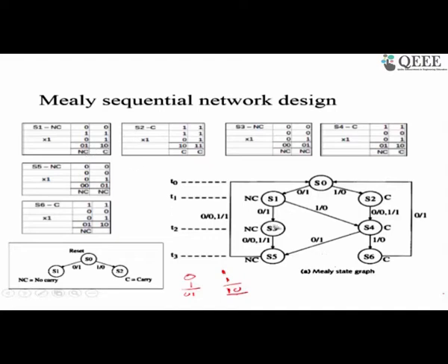So we will create a new state S3, call it the no carry state. How do we go? From S1, on getting a 0 we produce a 1 and go to no carry. That is what this transition represents. On the other hand, if a 1 comes, we should output 0 and go to a state where we remember a carry.